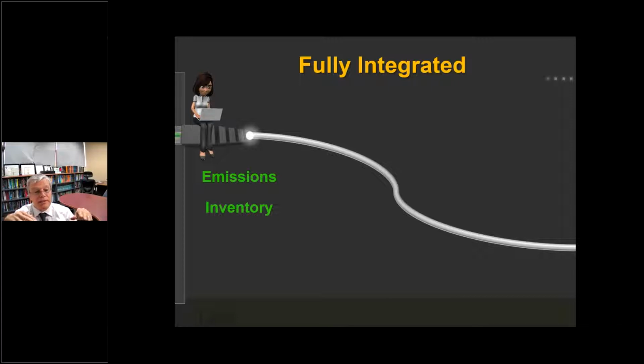So let's say it's an oil refinery. So we know how much is being emitted of benzene, for example. So we can dynamically tell what the operation needs to be. Let's say it's SO2. So if we have the estimate of what the emissions are with the current fuel and production levels, we can then run dispersion models and identify that we have a problem.